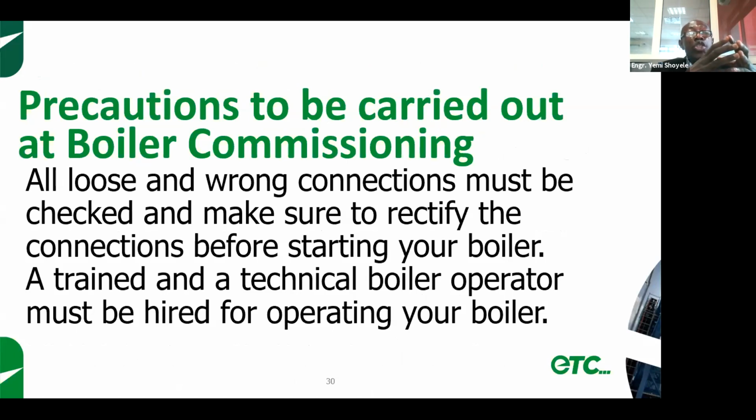Then also, you need to check all electrical connections. Make sure that you check all loose and wrong connections, and make sure you rectify any connection before starting your boiler. But more importantly, to operate any boiler, you must have a trained and technical operator. You have to hire a trained and technical operator, not a basic secondary school graduate. No, you have to have a technical person.